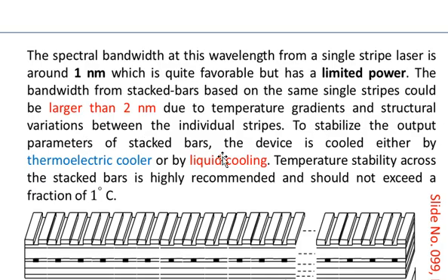To stabilize the output parameters of stacked bars, the device is cooled either by thermoelectric cooler or by liquid cooling. The temperature stability across the stacked bar is highly recommended and should not exceed a fraction of 1 degree Celsius. So you see that we can use stacked bars in order to pump the Nd:YAG lasers.